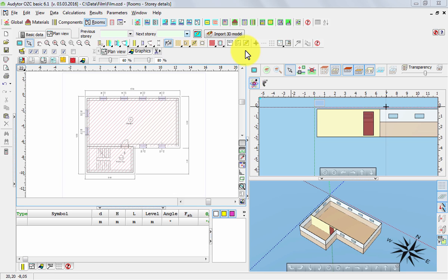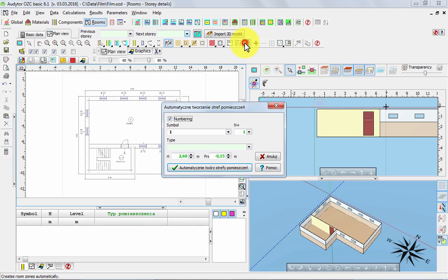It's very tempting to use the last method because it's the fastest. However, in this case, we don't have an easy way of controlling the order of numbering the rooms. So a lot of people prefer the second method because it's still quite fast, but by clicking the rooms in the right order, you can control the order of the rooms. In this case, we have only 2 rooms and quite specific, so let's use this last method, and then we will be able to renumber the rooms manually.